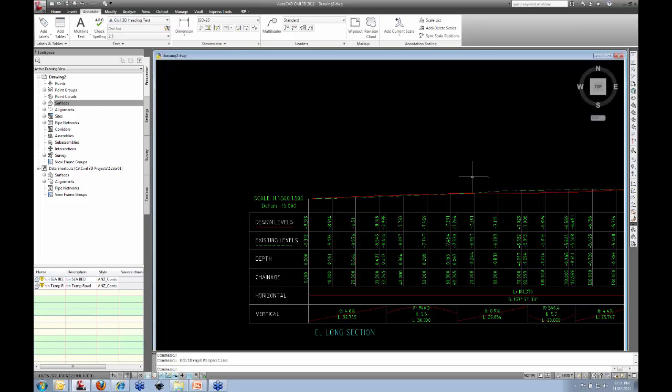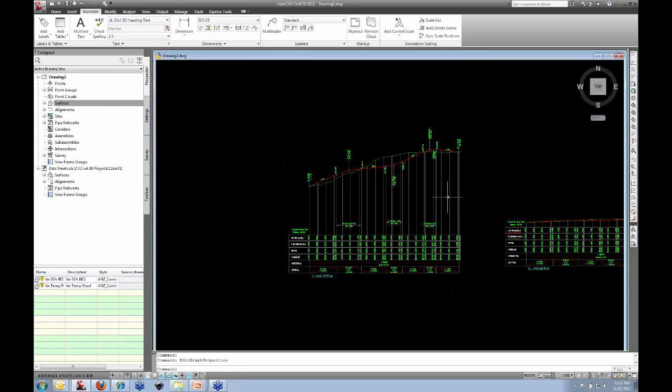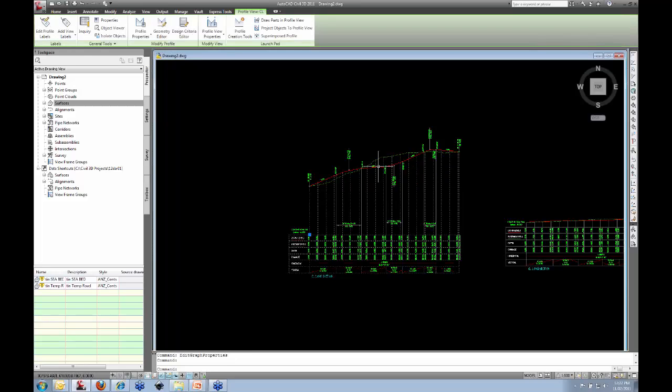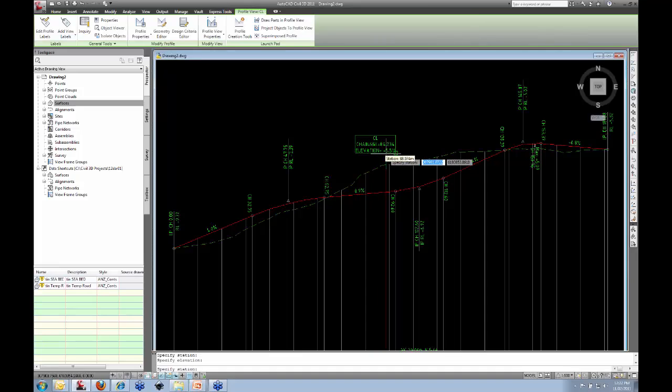Now one of the challenges in CAD is when you have vertical exaggeration turned on, it becomes difficult to label heights and everything else. That's actually in the software as well. You select here, and you have add view labels, station elevation, and depth. So if you go for station elevation, you basically pick the point you want, and it just puts a label here.